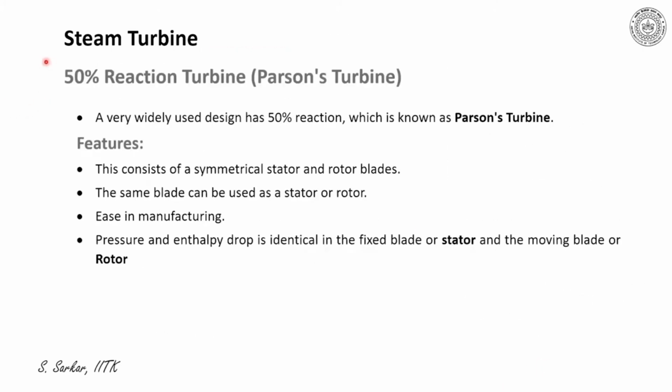After the definition of degree of reaction, let me discuss the 50% reaction turbine, which is called Parsons turbine. Please note that a very widely used design has 50% reaction, which is known as Parsons turbine.